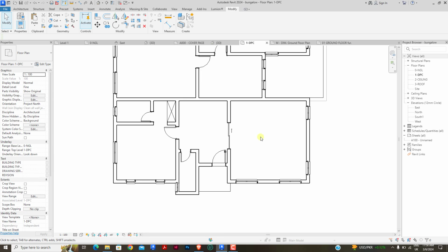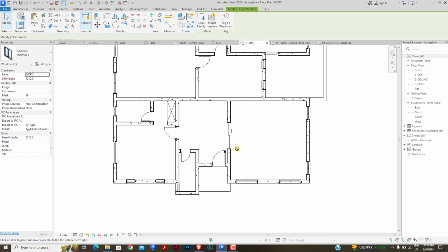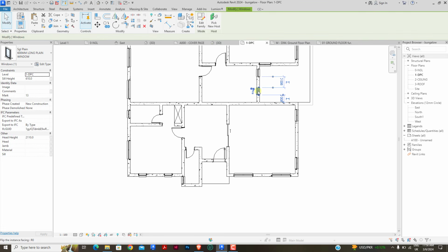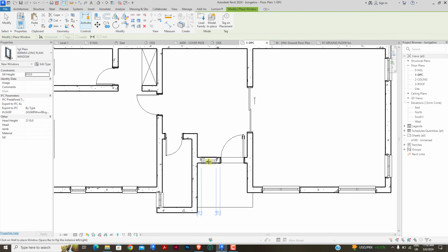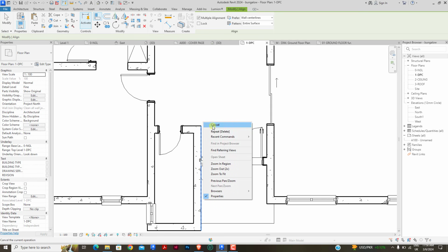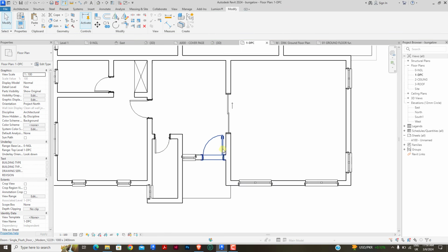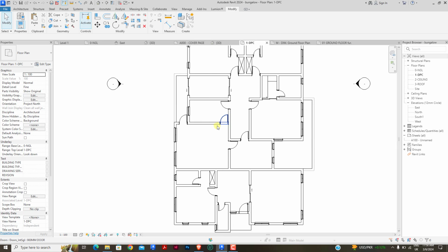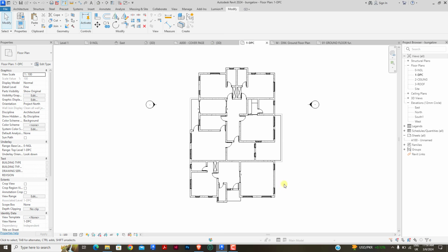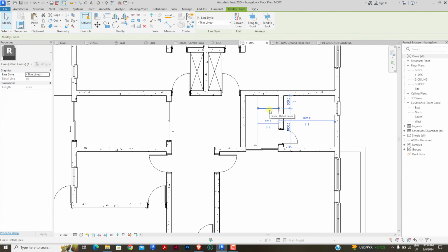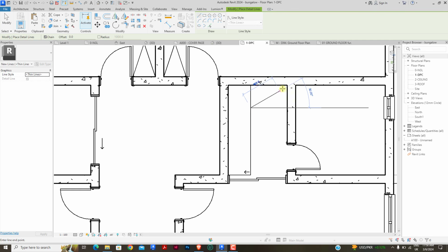Okay, then 900 window, just place one. Okay, let's use the smaller one. Let's use this 600 window, long windows. We'll place one at this point, attach it, align it to the wall. Good, perfect. All right, so I think that's all for windows and doors. We are done for windows and doors, and everything is looking nice. So click on this CS. Let's draw the cabinets.